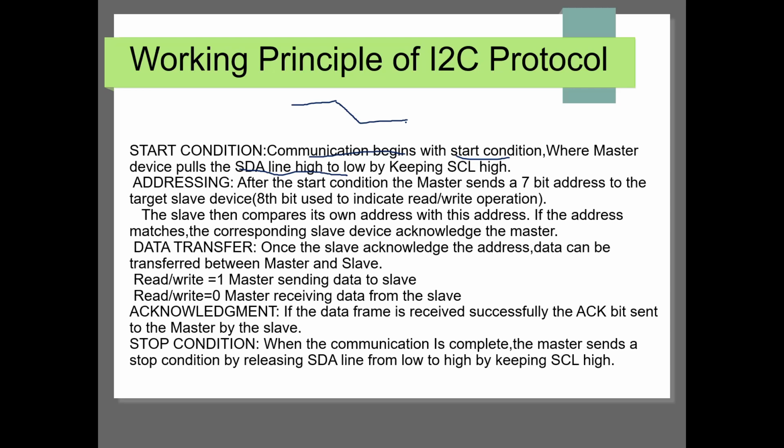This is the SDA pin. Okay, so this is the SDA pin. We are pulling from high to low. The master is pulling from high to low, while keeping SCL high. Okay, so while pulling the SDA line from high to low, SCL should be kept high.